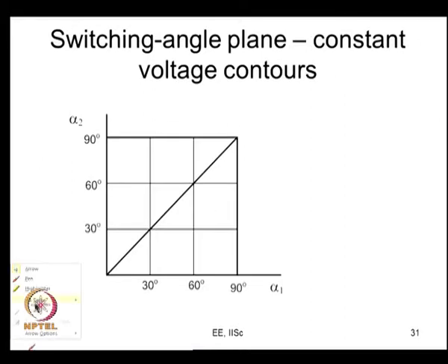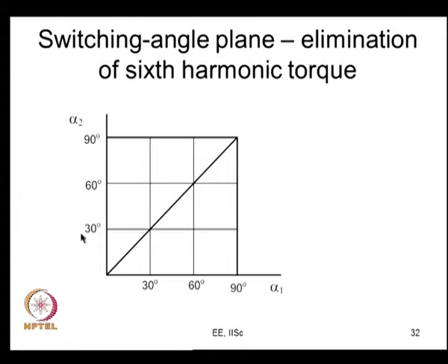And we can actually look at it on this plane which we had looked at long back. For example, this alpha 2 and alpha 1 are the switching angles, and this corresponds to square wave operation, if you recollect our earlier lectures on this low switching frequency PWM, and this line would correspond to something like V1 is equal to 0 per unit. So, a particular fundamental voltage will go like this, that is, all the points along this line would actually give you a particular fundamental voltage now.